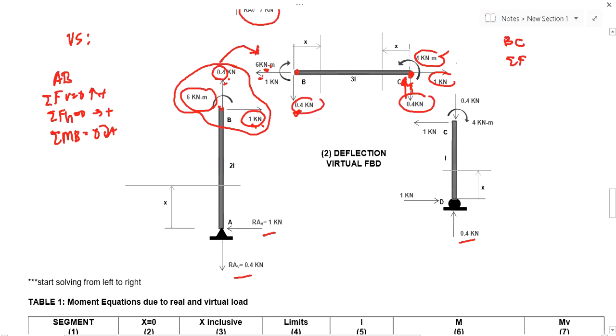Okay? So whatever we solved here, that is also what we will put at CD. Okay? Opposite direction. So if upward, here in BC, our C, the reaction at C, is downward here. If to the left, it becomes 1 to the right. Okay? And counterclockwise becomes clockwise here. Okay? And if you take the summation forces, our equilibrium equation, everything should be zero. Okay? Summation forces vertical, 0. When you take moment here, at D it should be 0. Okay? Because we have no moment here.